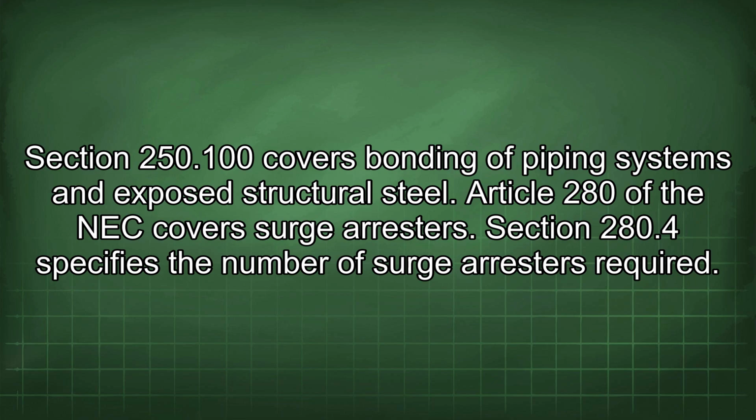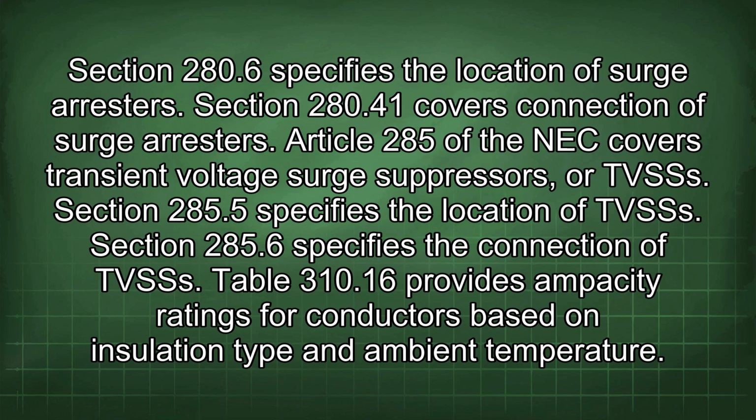Article 280 of the NEC covers surge arresters. Section 280.4 specifies the number of surge arresters required. Section 280.6 specifies the location of surge arresters. Section 280.41 covers connection of surge arresters.